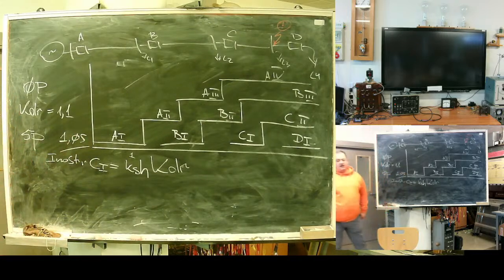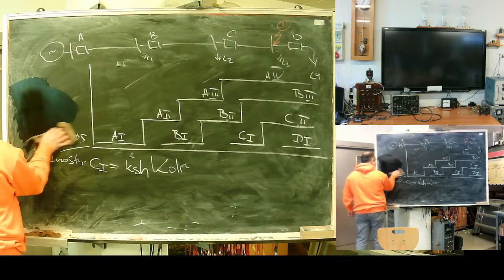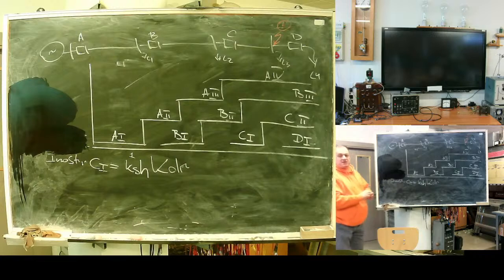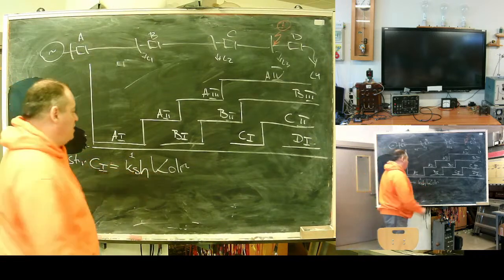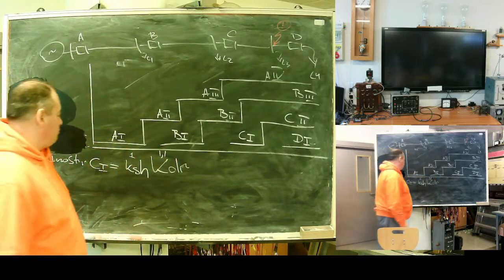So it's a safety factor for the error of your transformers. Usually relays are more precise than current transformers. So this is safety. I assume an ordinary transformer, 1.1.